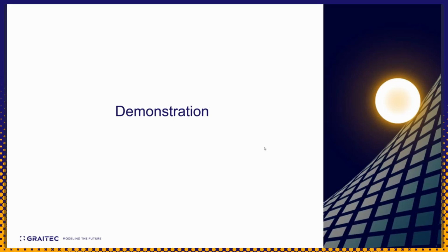Your analytical model should be properly created first before sending to Advanced Design and any structural solution, because if you have any discontinuities or offsets or eccentricities where your members are not connected, basically you cannot run a structural analysis on that. So before that, you will need to fix your analytical model inside Revit, which my colleague Ciara will show you right now. Ciara, please, thank you.